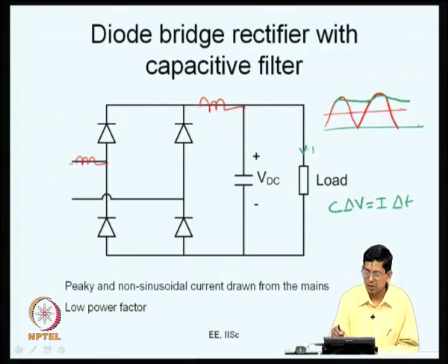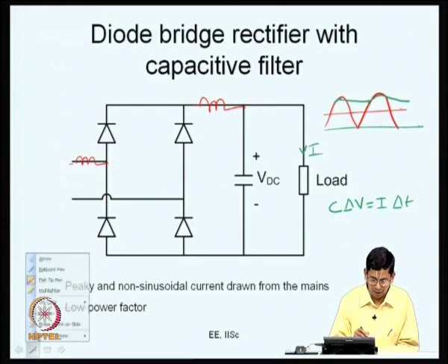During that time the capacitor is getting discharged by the load current I that needs to flow, and this delta V is the acceptable ripple voltage. So, you need a big enough capacitance to keep the voltage ripple small enough. That is what we are trying to look at. This is how you basically choose a capacitance, as you all would know very well.